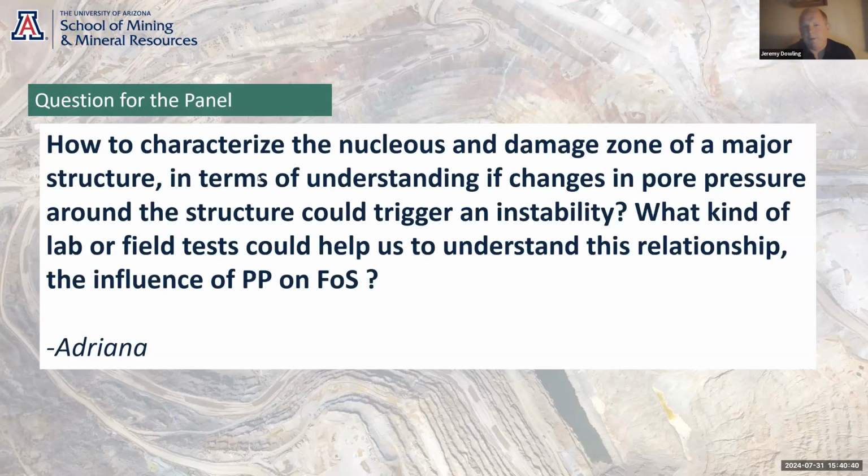Yeah, for a major structure in a pit slope design, the only way you could test the relationship between the pore pressure and the factor of safety would be if you had a good understanding of the fault properties, and then you could do a sensitivity-based analysis in a slope stability or deformation model to understand what ranges of pore pressure or changes in pore pressure could change the factor of safety on the fault.